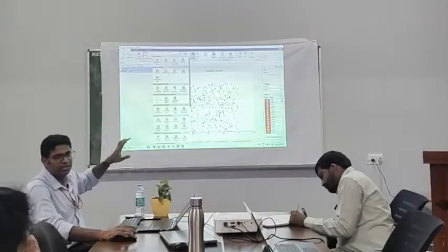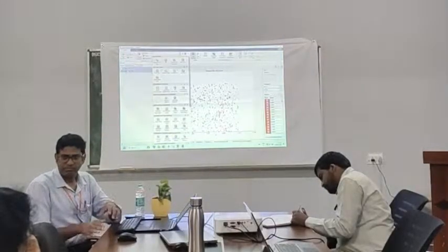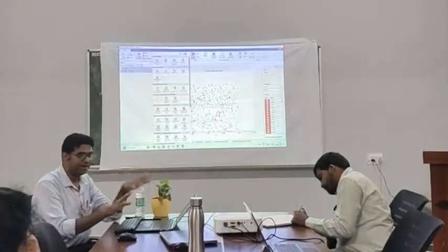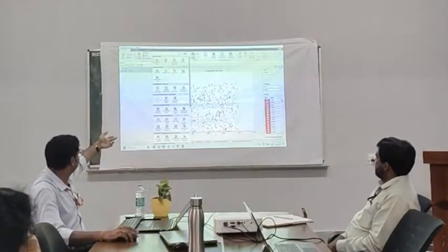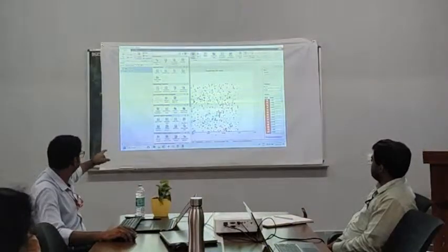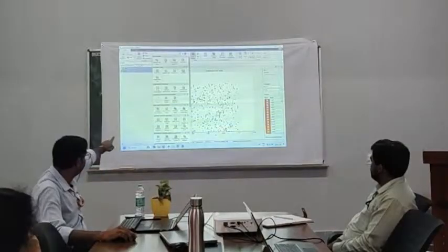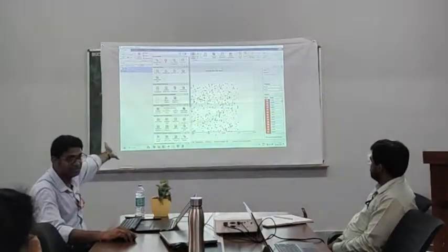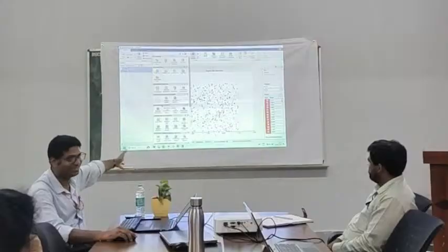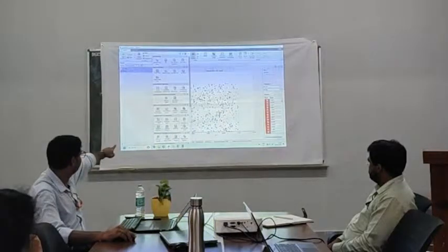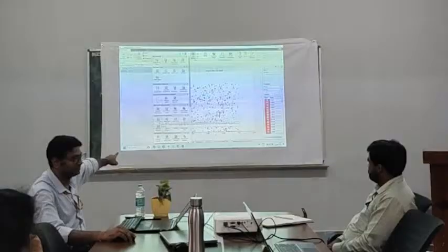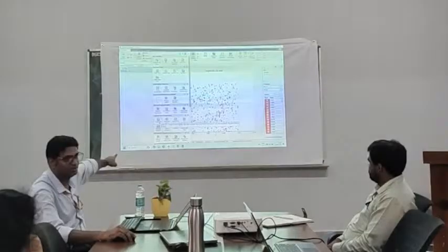If you open any MATLAB platform from version 18 onwards, trees will be given by default. Depending on your need, you want SVM. You can add Bayes effects, the Bayes probability, box plot, everything will come. So I go for SVM. You see here it is Linear SVM.